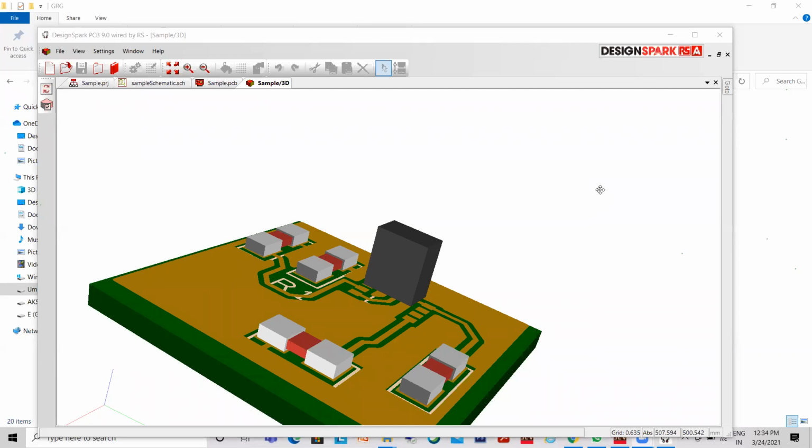What are nets and power plane? Nets are the signals, actually, Akash, and nets can be the same signal from one pin to whatever pin it connects. So one signal can pass to many components like capacitor, resistor, or relays, whatever it may be. So the same signal is considered as a net. And the power planes are the copper pour, like the ground plane I have poured, right? So that is actually a plane concept. So instead of making the trace connections, we are connecting this as a plane.